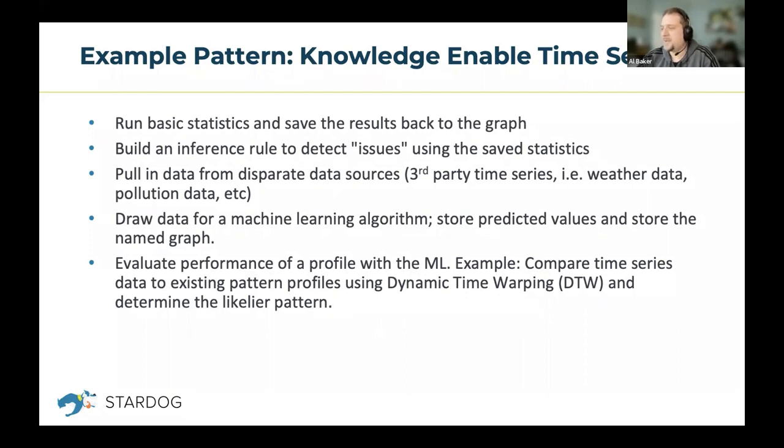But we're going to use dynamic time warping. If you're not familiar with that, it is essentially an algorithm that can elongate the x-axis. So if we have an engine running for different time periods, how do we compare those? Well, if we elongate the x-axis, then we can compare two curves and we get a notion of distance between them.